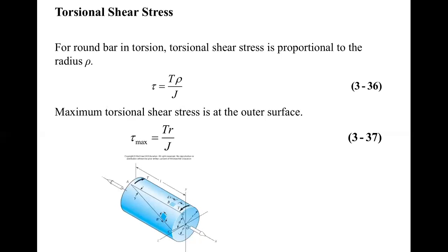And so now, let me give you a summary. If you look at axial loading, tension or compression, the stress is uniform. If you look at any point on the cross-section area, the stress will be the same. So when you do the design, it doesn't matter where you pick the location because the stress is uniform.